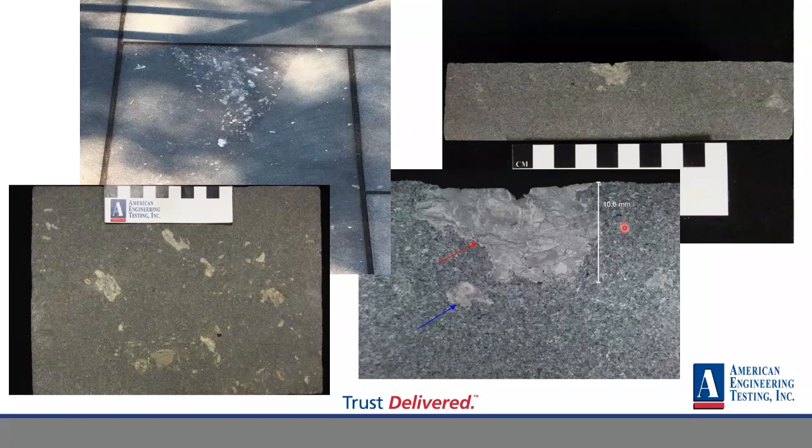And every geologist listening on this call should be able to raise their hand and tell me what hydrochloric acid does to limestone, because it is obviously a tool we all learned to use in our universities. So his cleaning product was starting to dissolve these and react with these lime mud clasts and cause this pitting. So the question becomes, whose fault is it? Was it the quarry who was producing this stuff, wasn't doing quality control and finding these mud clasts, or did the contractor use the wrong type of cleaning solution, but he didn't know those were there?